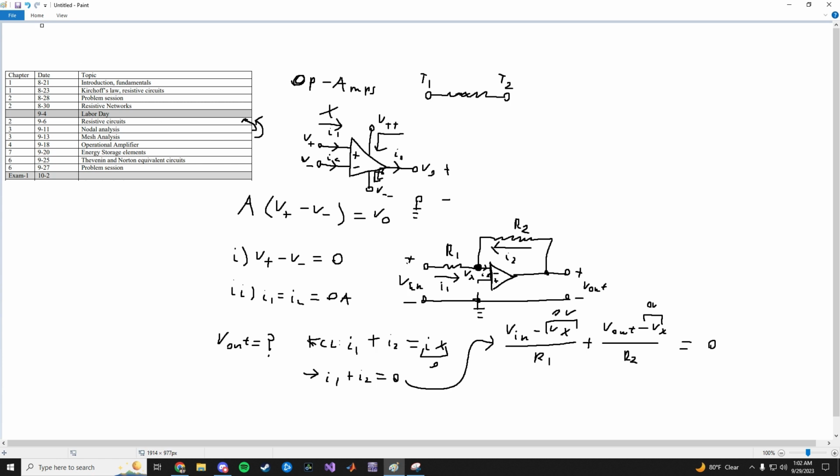But let's say hypothetically, because this might be confusing for people, I'll show you how it works. Say there's a voltage source here, Vs. Then using golden rule number 1, Vx would be pushed to the voltage Vs. So this Vs magically makes this node Vs. That's just how op amps work, the golden rules.